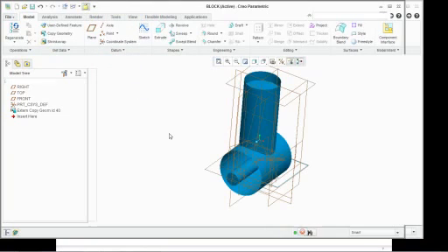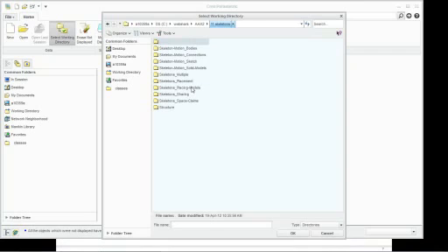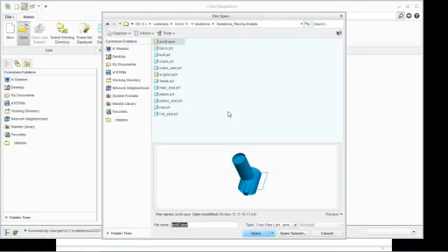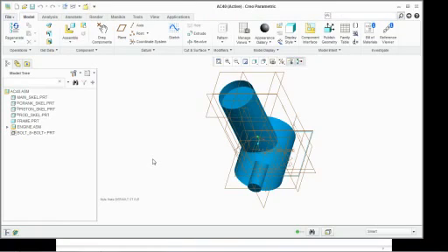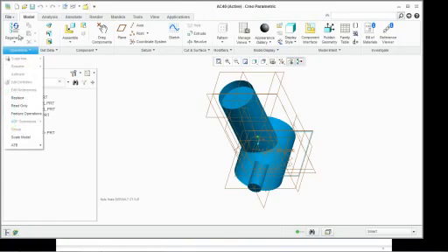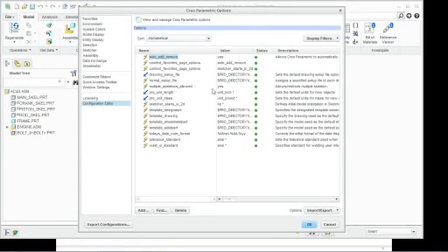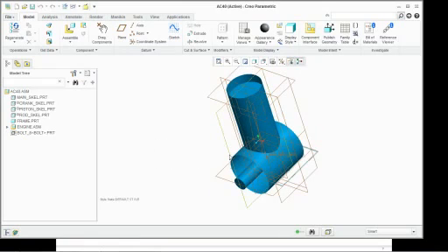So let's go ahead and close this one out here. Erase not displayed. And I'm going to go to skeletons, set my working directory, skeletons, placing models, and I'm going to open this first AC40 again. From here, I want to make sure, of course, that my allow all skeletons is still set to yes. Multiple skeletons allowed is still set to yes. Sometimes when you open different models, it may change.